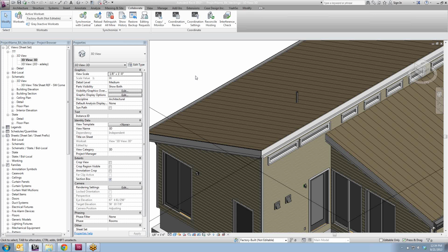I mean, correct me if I'm wrong, but the standing seam isn't something that they're going to install in the factory. My guess is you'd have the whole mod assembled on site with the SIP in place, and then the roofer is going to go up with the sheet, run it down the roof, cut it at the end, and then come back with the seaming machine to get everything weather tight and integrate it with the drip edge and everything like that.